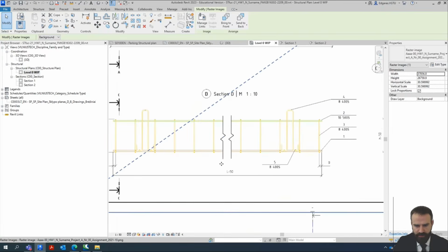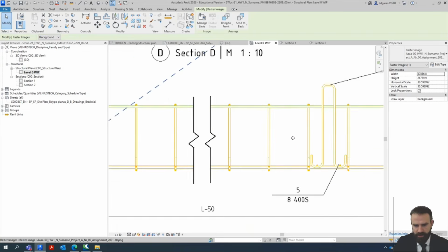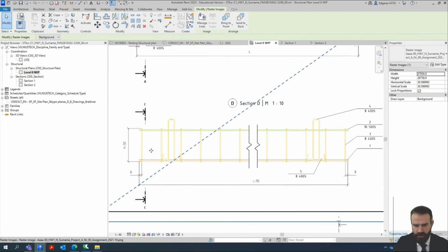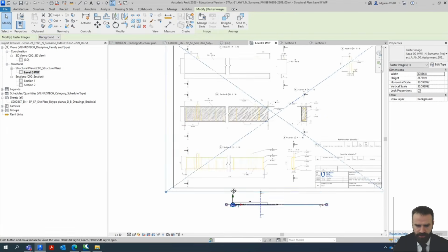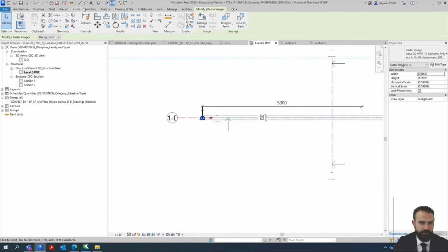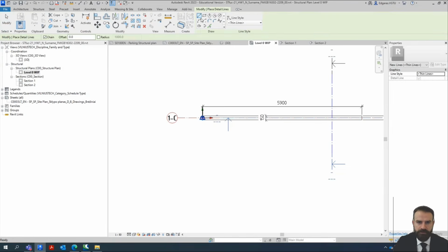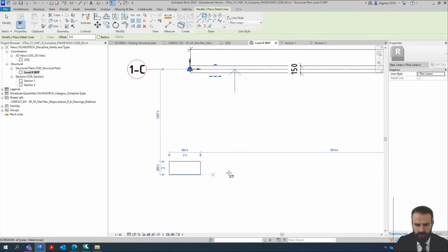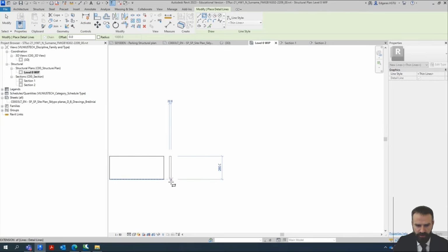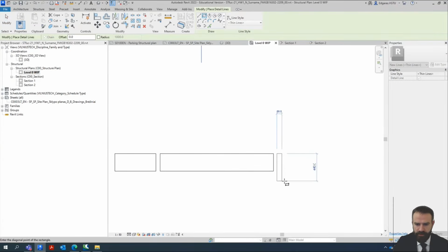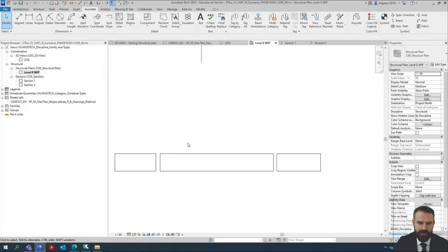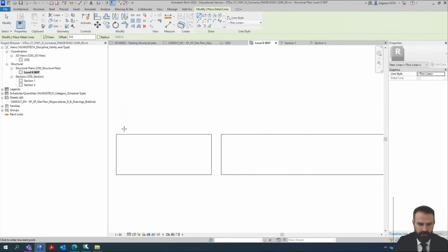So now regarding reinforcement. So the spacing between bars is letter T. How many spaces is letter N? And letter M represents, if we have, let's say, how to draw it, just maybe simple annotation tool. So normally beam reinforcement goes in 3 segments. So in one segment we have dense reinforcement placement, and in other segments we have not so dense. So let's say in this location I have reinforcement bars which are placed quite dense.